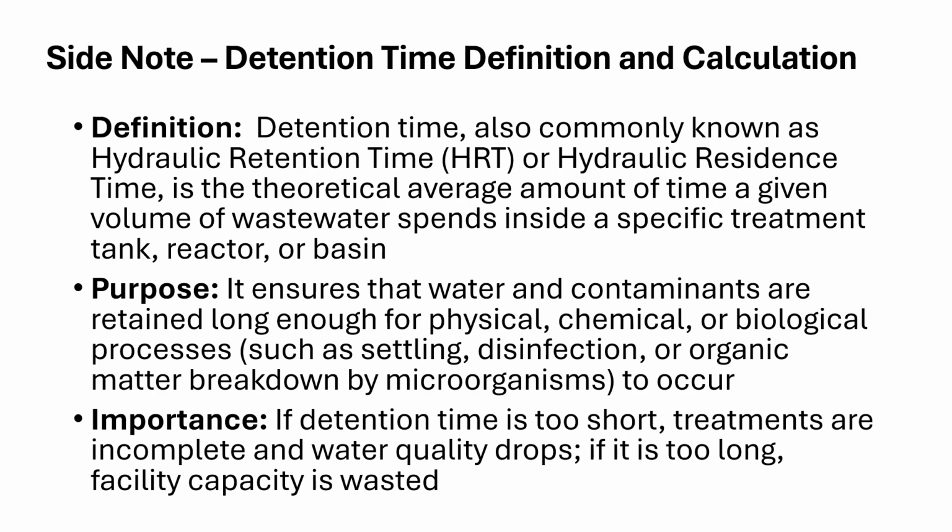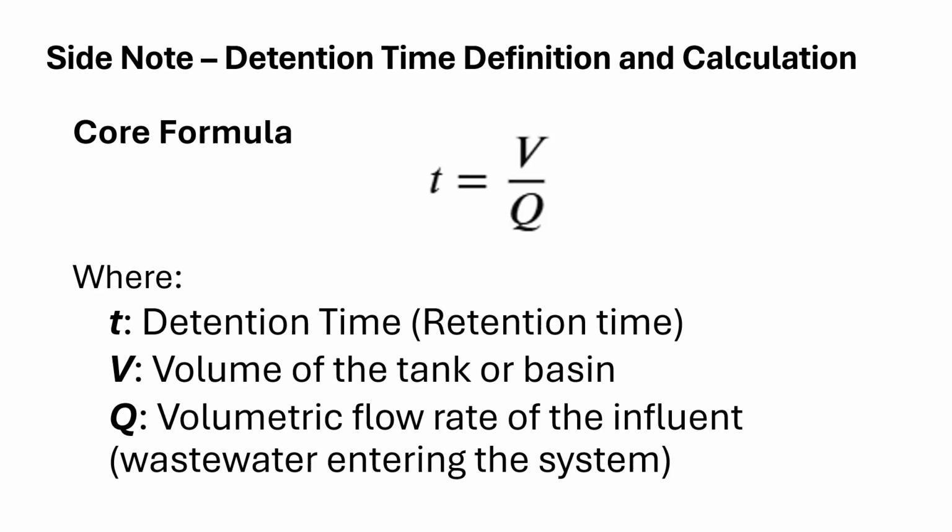So there are downsides to detention time being too short, which is the process doesn't have time to fully take place. And there are times where detention time being too long is a negative, because in that case, we're basically keeping our entire process or facility idle because of a longer than necessary detention time in a certain process.